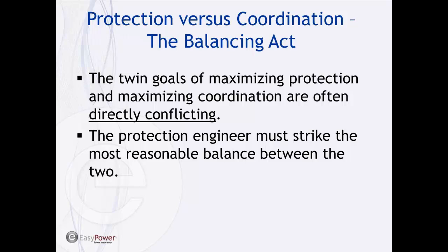When we talk about a balance between the two, maybe under normal operation selectivity is a requirement, but during the maintenance or the energized work, the implementation of equipment and protective devices with maintenance mode settings is a viable option, where a maintenance mode setting is activated just while the maintenance is being performed, and then once it is complete, your system is put back into normal operation.